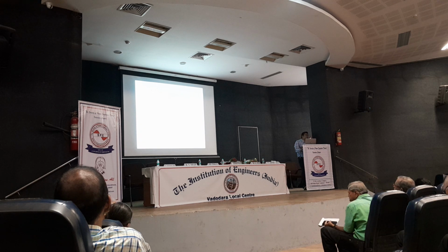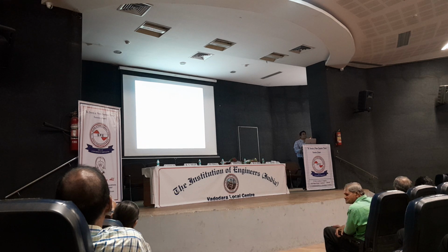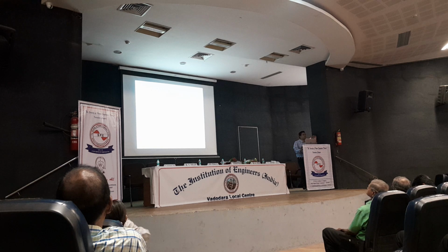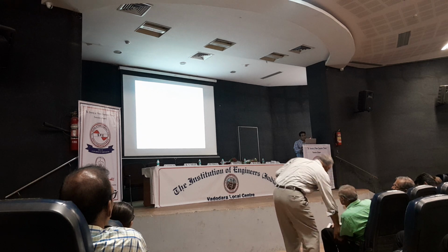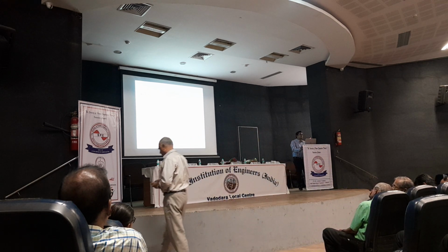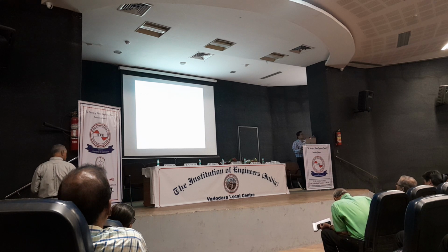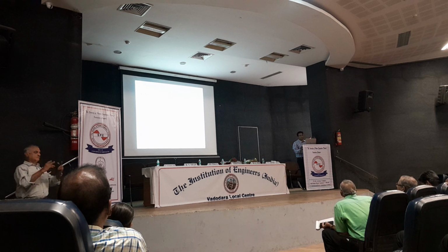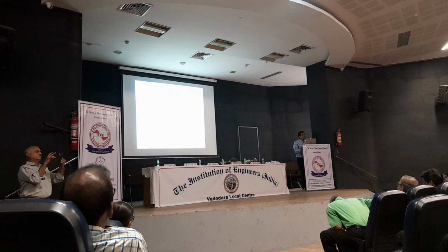And whenever we are doing this kind of fault analysis, one thing is clear: we are making the assumption that fault current is only flowing through the faulty phases. In the other phase, by default we are assuming that there is no flow of current. If we keep that in mind, we will match our theoretical results with these practical calculations. So this is a complete PowerWorld simulator package. I have tried to cover the case studies along with how to deal with the software. So thank you everyone. Thank you very much.